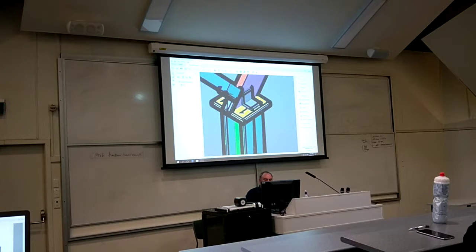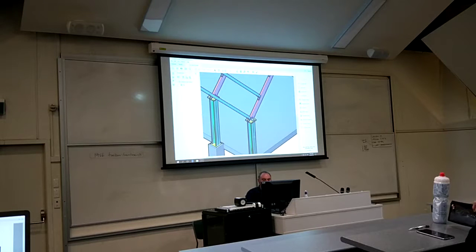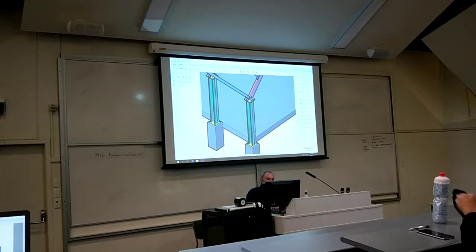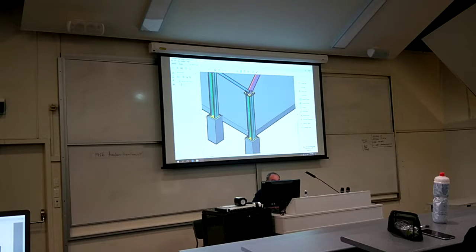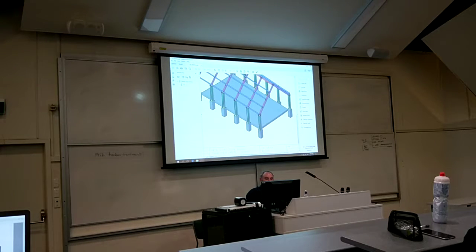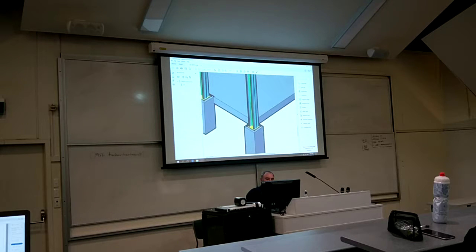Then you've got your steel, which is down here. You've got a steel plate that's welded onto a column. Talk about all this in our notes section. There's a steel plate at the bottom. You'll be designing these plates according to some of my notes that you'll get next week, and you'll be putting bolts in them, bolting them down through into the foundation. This is nothing like any other assignments I've done before. You'll see the foundation slab is quite separate to the piles.